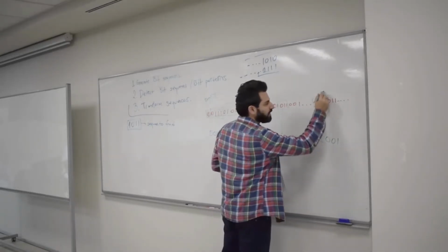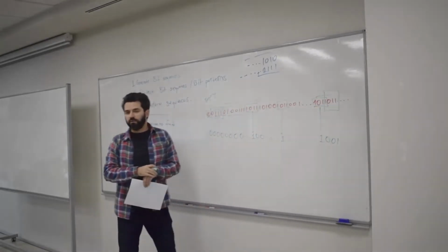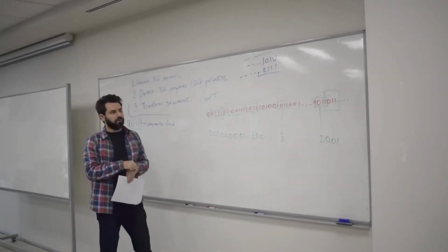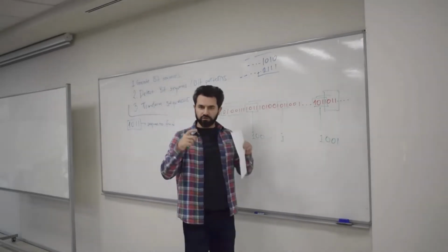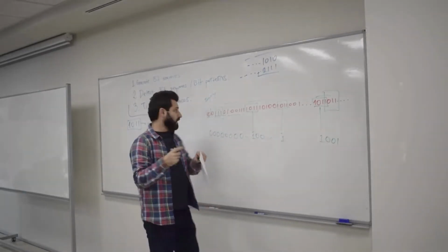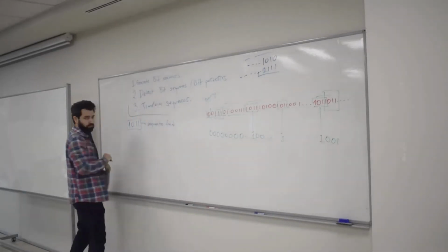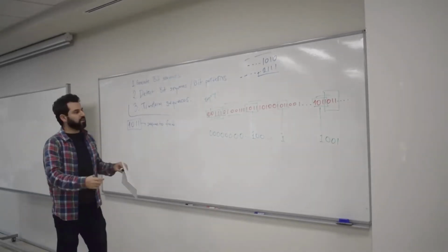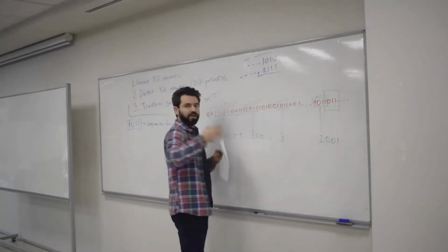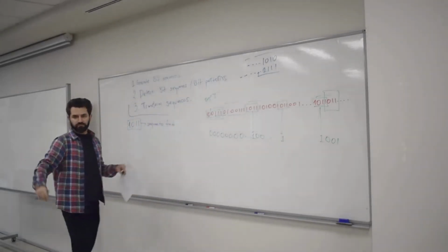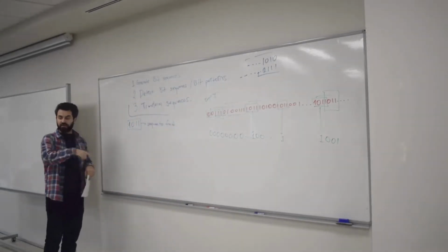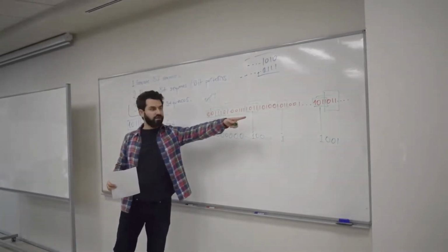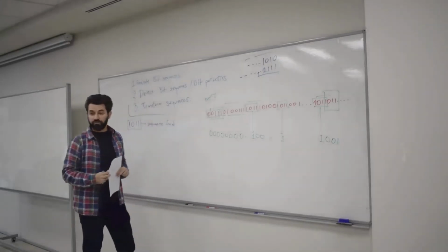But those windows actually overlap with each other. So you might want to think about that, because even though the windows overlap, they can still contain a valid sequence. Keep that in mind. All these windows need not be separated. So when you draw your state diagram, which I will do right now, I'm going to take this into account. That's a very, very interesting observation.